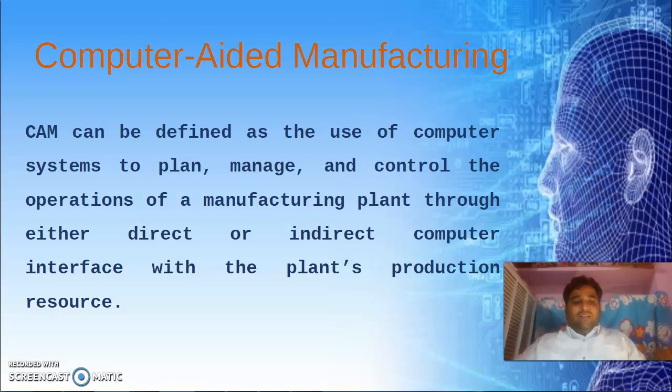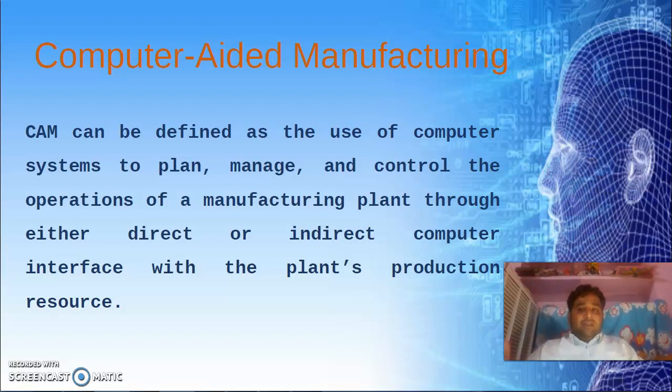The design is available in your CAD module like Creo or CATIA. This can be directly imported into the CAM software. The CAM software will have a setup of your machine also. It will have inbuilt inputs of your machine, so whether it is possible to do the manufacturing operation on that machine or not will be said by the CAM tool like Mastercam. If it is not possible to do the machining operation on your existing machine, it will be directly alerted by the CAM tool.